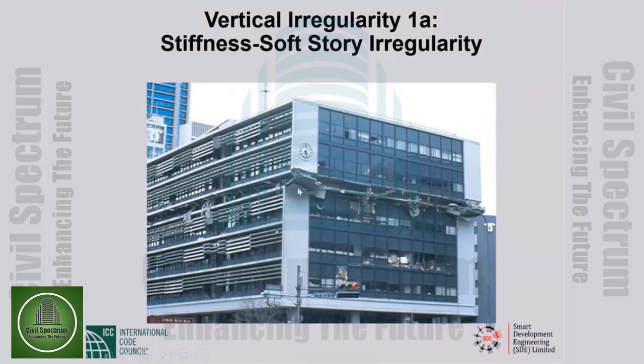And this is a very, very good example of that. I think I showed you that the day I was talking about earthquake experience. This is the City Hall of Kobe. The bottom part of the structure has steel reinforced concrete. The concrete has steel shapes concealed within them. But at that level, the steel shapes were discontinued, giving us a stiffness discontinuity, and that is the level that failed.